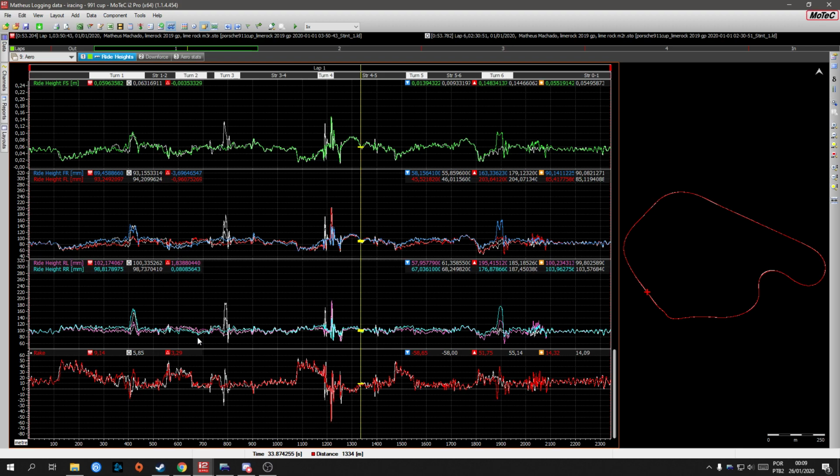basically, you want to look at high-speed corners, and I'm talking about going above like 150 and 160 to generate some kind of downforce. There you want to worry about aero, and increasingly more as you, let's say, have a 200 kilometers per hour corner, you want to worry about aero even more there. So yeah, if it's a high-speed corner, you should look at tuning your aero.